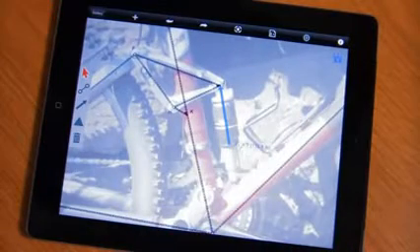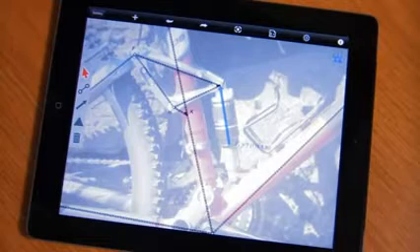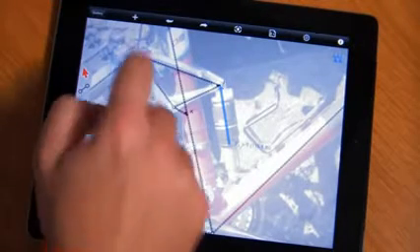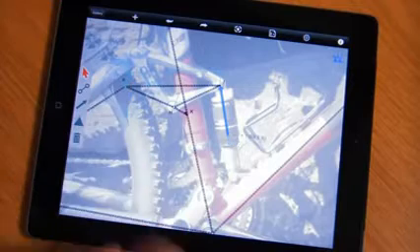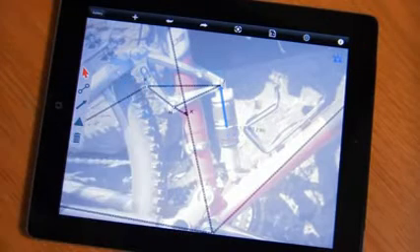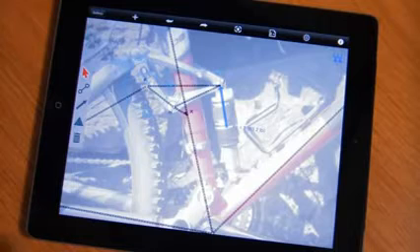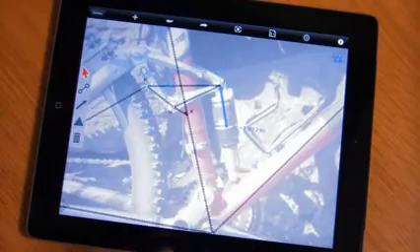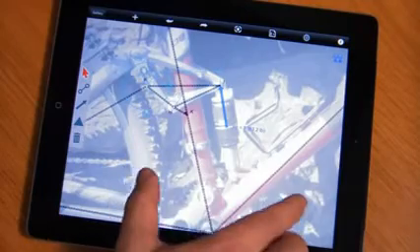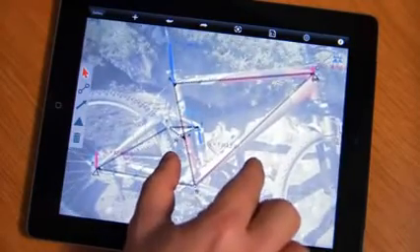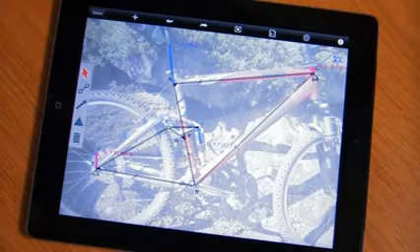So the design intent in this case was to try and minimize or get a lower than 115-pound reaction across the system. So the user can simply start dragging and manipulating the design to try and minimize the force. Notice, without ever having to worry about setting up the problem again, the user is able to iterate in a conceptual state to come up with all kinds of different potential design solutions with minimum problem setup. So here he's got one that gives him an 83.2 pound reaction at the piston, allowing him to use a much smaller piston for the design.